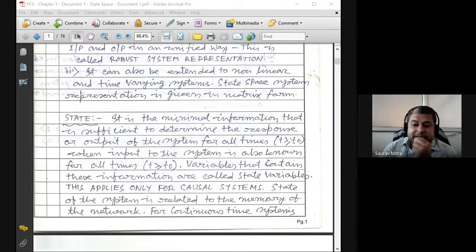You can. That is right. Okay, the only thing we have to see is which parameters are changing with time. If v(t) is the instantaneous input voltage and i(t) is the circuit current, then whenever there is a change in v(t), i(t) will change. Whenever there is a change in v(t) with respect to time, v_C(t), the capacitive voltage, will change. And v_R(t), the resistive voltage, will change.